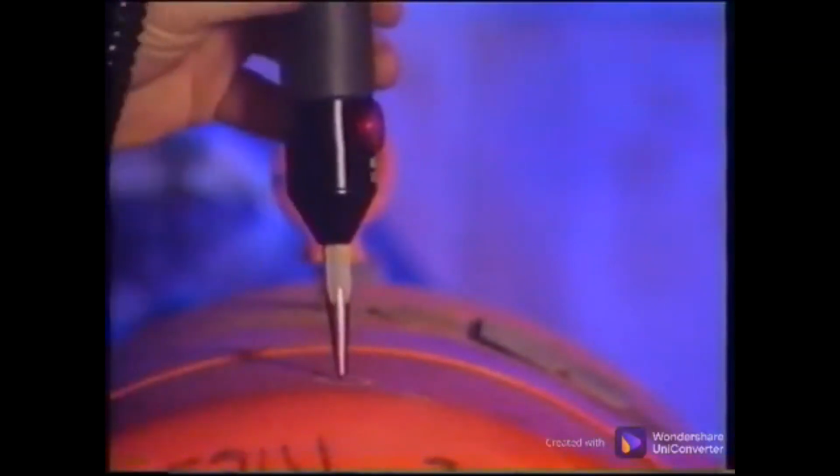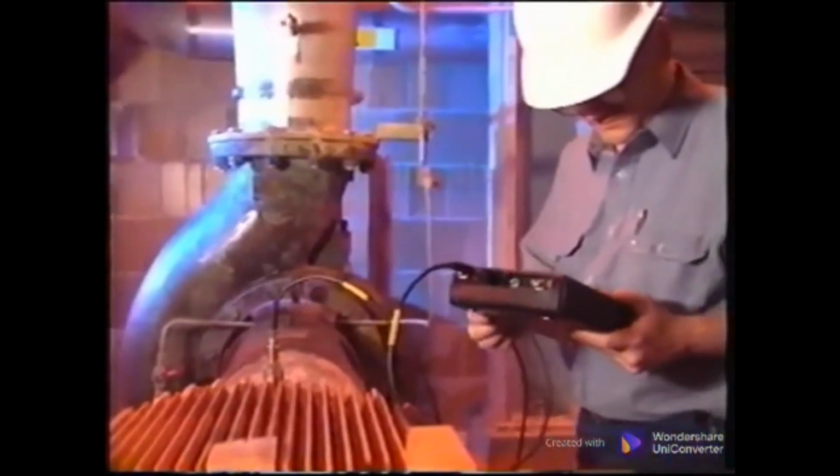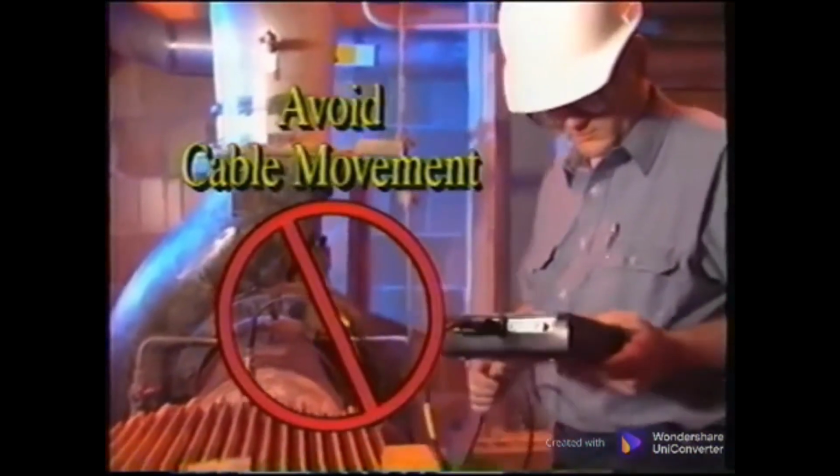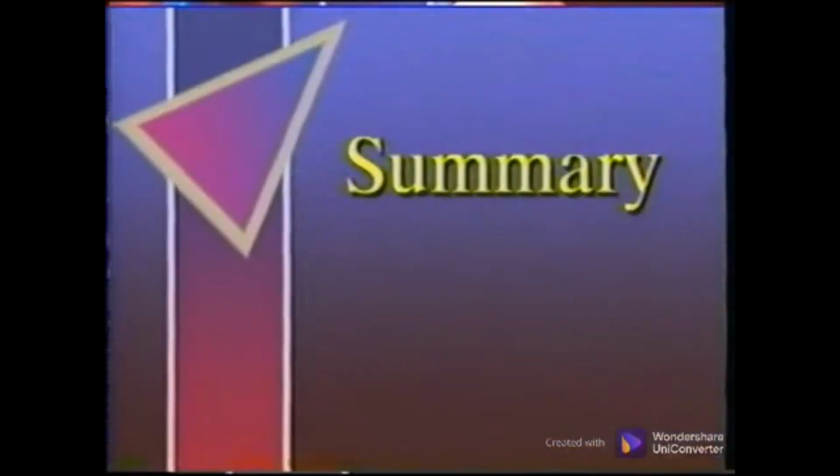or cable movement. The ski slope is especially common when data is acquired with a stinger because of the slight continual movement of the hand and cable. During data collection, be sure to avoid cable movement, as that may add a ski slope to your data, causing unusually high readings.